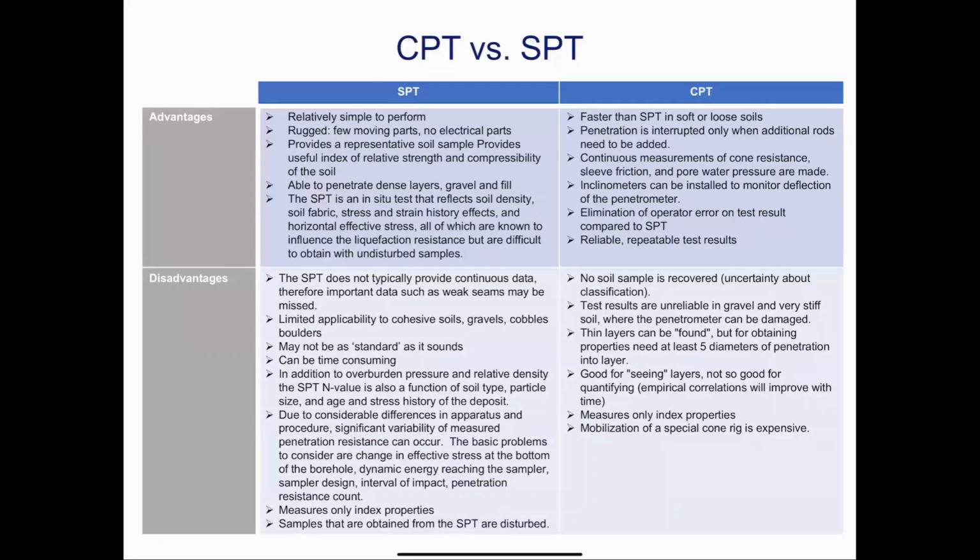SPT testing is better than CPT in that you can get soil samples. You can get some soil inside a split spoon, even though it's highly disturbed, and you can only have limited use of the soil. There are probably way more correlations that you can use in Hong Kong with SPT data and values because we construct the land a lot more than we do offshore with marine deposits, right? So if you look in the literature and existing projects, you'll see a very rich database for blow counts for SPT compared to CPT for strength and compressibility.